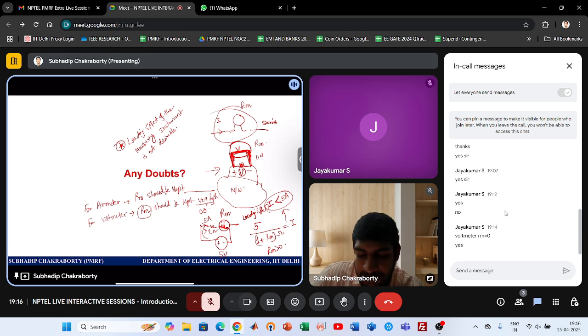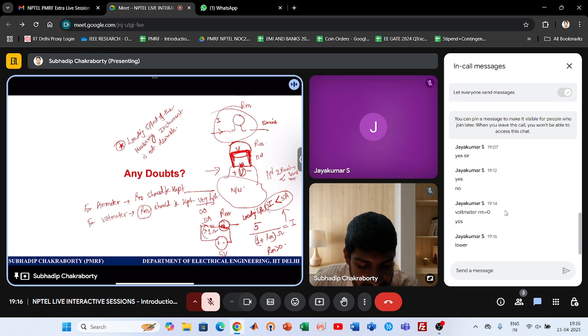You know that the parallel combination of two resistances is less than the lowest resistance. You should have known this: the parallel combination of maybe infinity ohm and 2 ohm is almost 2 ohm. So it is not having any loading effect.